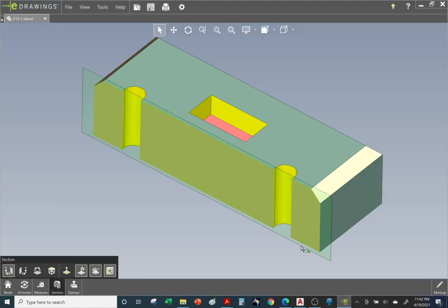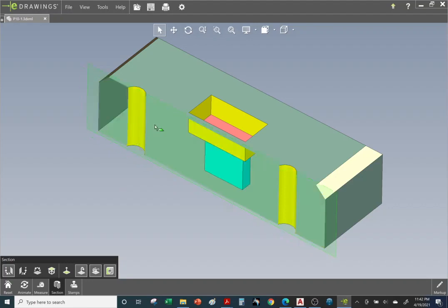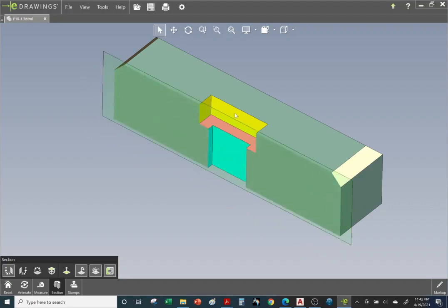Let's go back to the 3D model. Okay, so the holes, that's open space. You do not hatch those areas. Only when you're cutting through a solid, that's where you do your line hatching. Let's keep going through the counterbore hole. So the counterbore hole, that's an open space. We do not hatch this area. We hatch only the areas where the teeth marks are left behind by the saw, right? Okay, so let's go back.